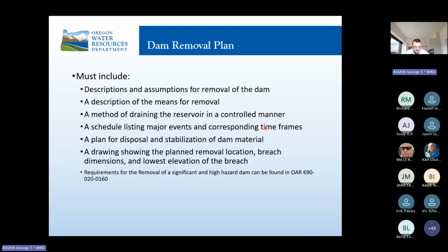And so generally, we're looking at these plans from a safety perspective. Where dam removal may be just a notch of the dam and not a complete demolition of the entire dam, we would look at the remaining soils or slopes to ensure that there's not a condition where we may have some slope instability or a slide condition where that soil could slide back down into that stream bed, creating a dam situation again, or a condition where maybe there's unstable soils that could easily erode downstream.